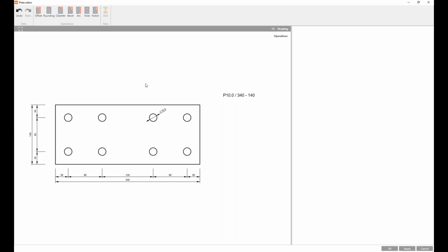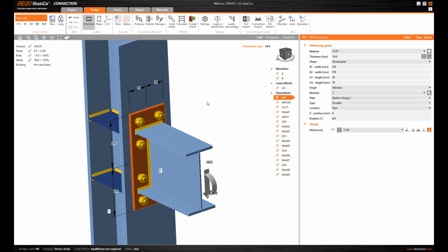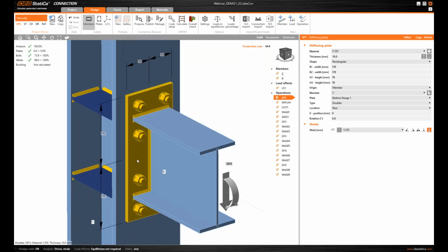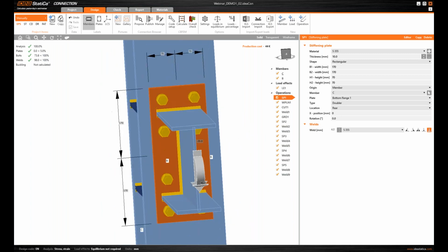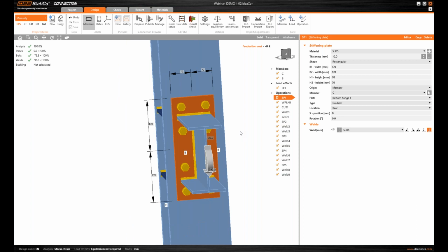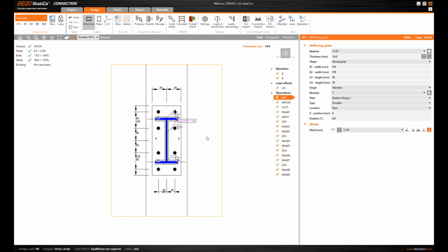Maybe also if you click in the 3D model or select some operation, for example select the end plate, it shows you the dimensions in the 3D window as well, the basic ones, yes. And what comes to my mind, the third option, if you right click on the end plate and create a section, then it also provides you the dimensions and also some simple sketch or drawings that can be printed out into the report.